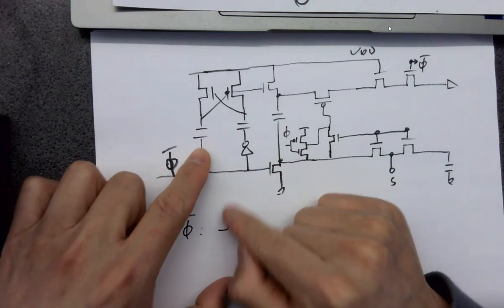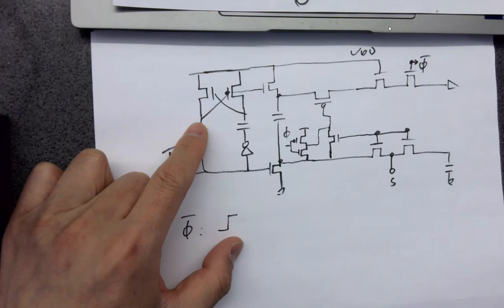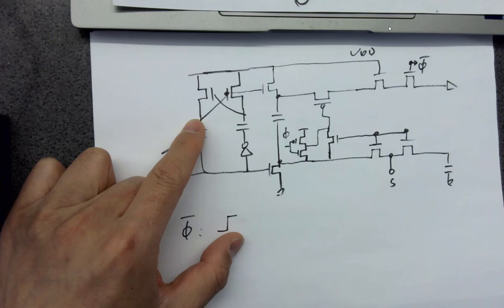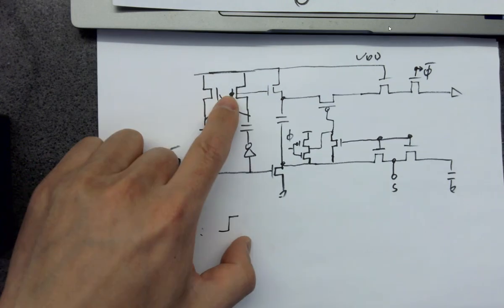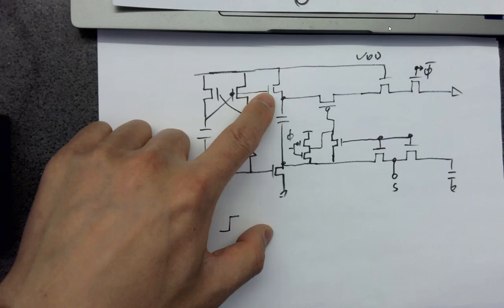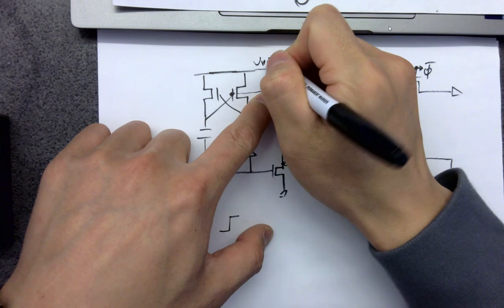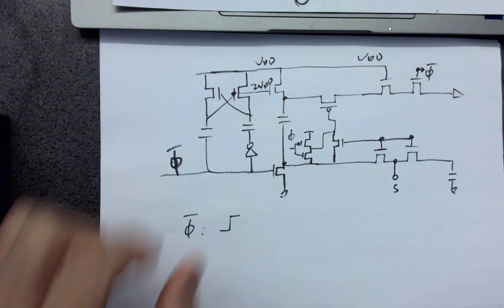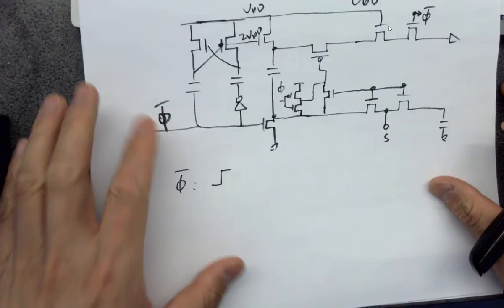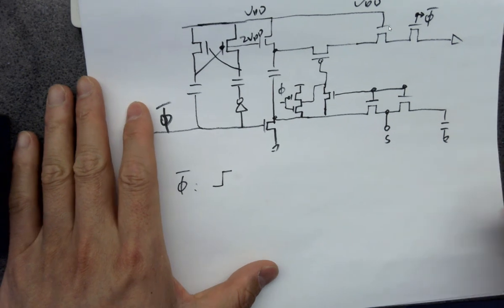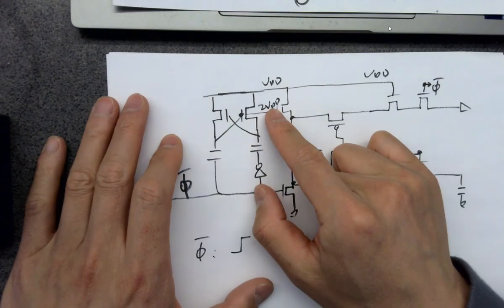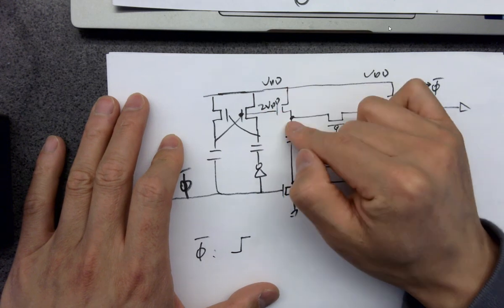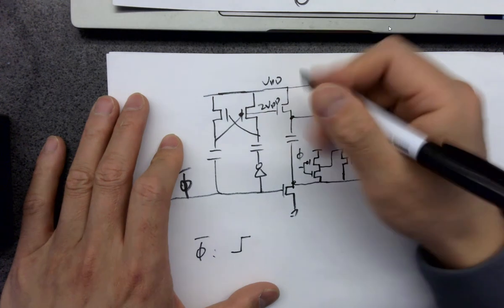If the rising edge is pushing, you are getting a 2 VDD, right? So 2 VDD arrives here and arrives here as the gate voltage. What's happening? Remember, for the NMOS, if you have the gate voltage higher than VDD, you are able to pass the entire drain voltage to the source. You are not losing VTHN, okay? So this one becomes VDD.